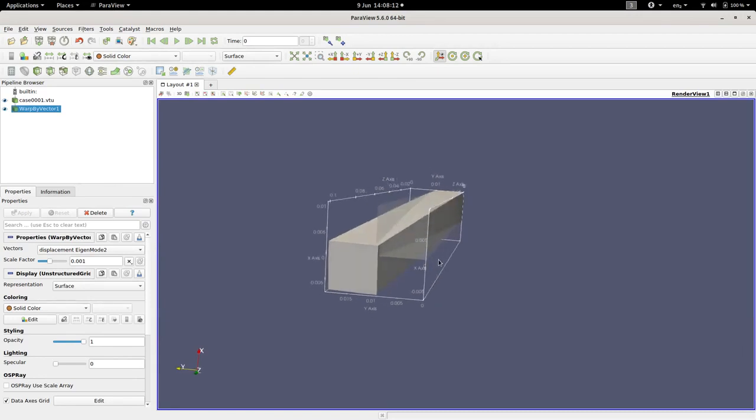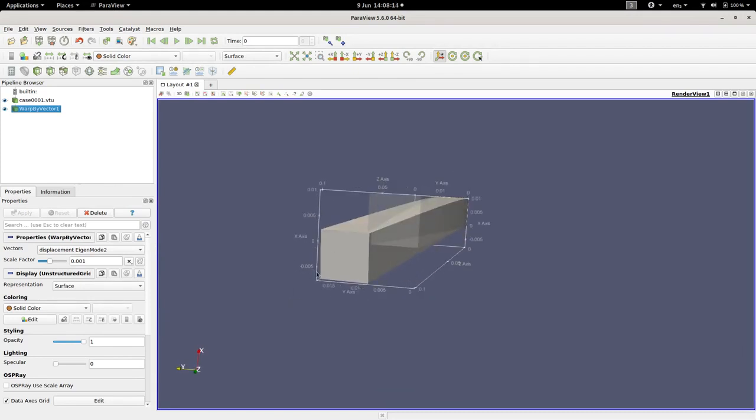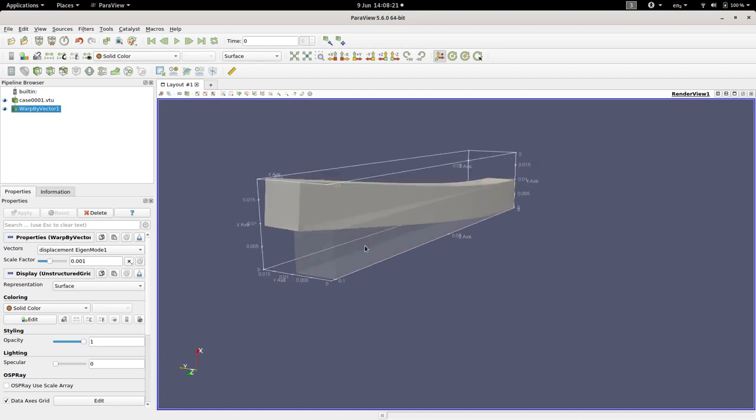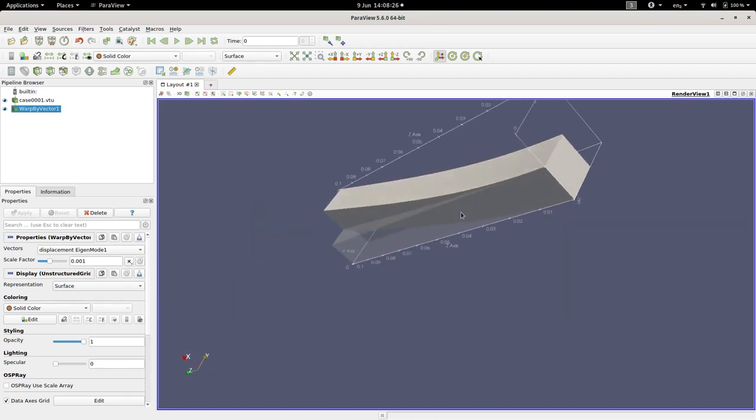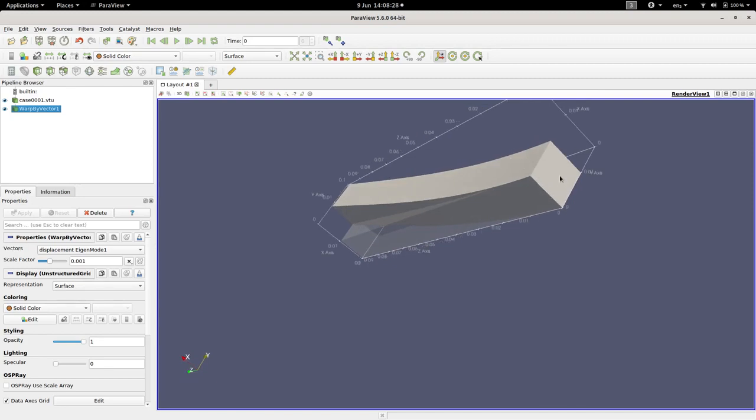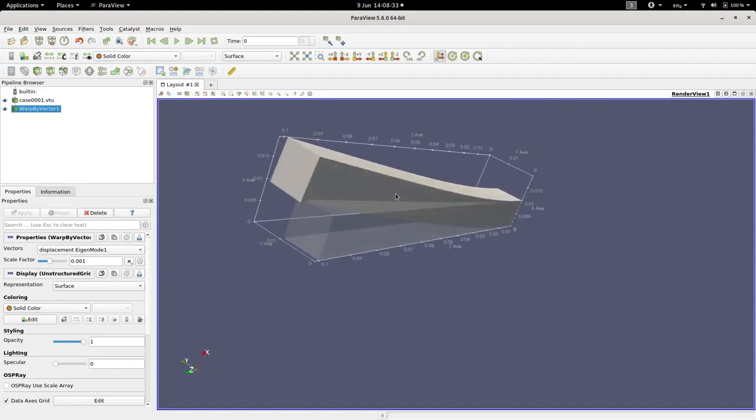It is just that the bar is vibrating on the same pattern, but along two different directions. And the ambiguity is probably given by the fact that there is only one strong boundary condition in there. If we add more boundary conditions, we constrain the number of possible vibrations, and so we will have less modes of vibration available for a single resonance frequency.